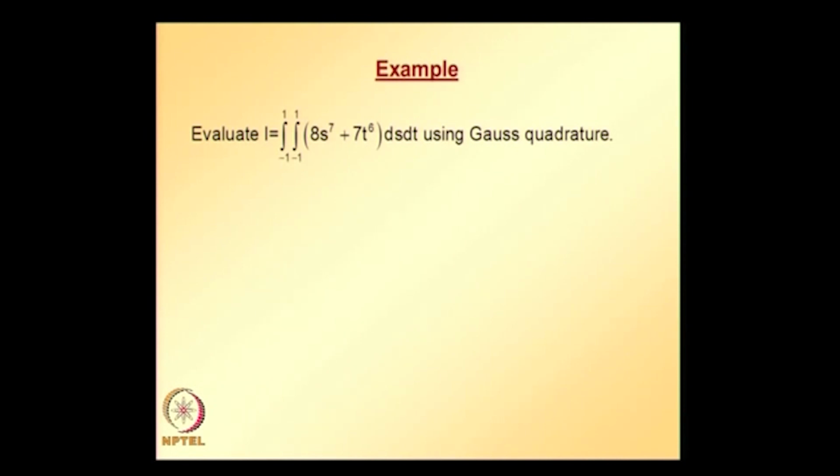So, to evaluate this integral accurately we require 4 points along s direction and 4 points along t direction, and if we use fewer points we get error.